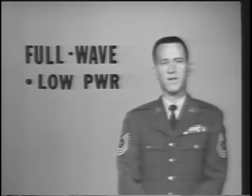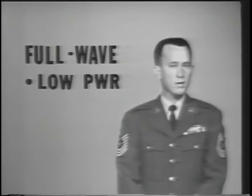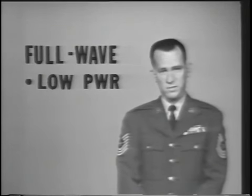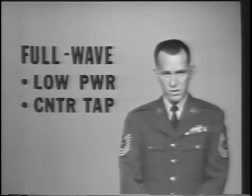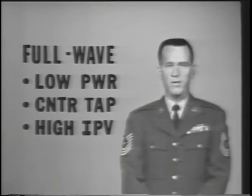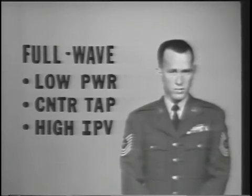Even the full-wave rectifier has its limitations. Though able to supply more current to the external circuit than the half-wave, it is still a relatively low power device. And because it requires a center-tap transformer, only half the available secondary voltage is felt in the output. Another limitation of the full-wave rectifier is the peak inverse voltage applied to each non-conducting diode.